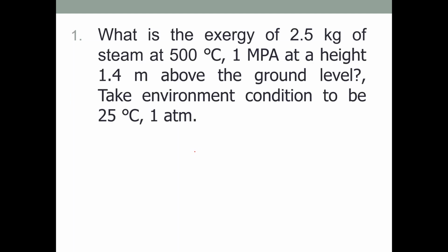Now we can apply this concept for solving different numericals. Now if you see the first numerical, what is the exergy of 2.5 kg of steam at 500 degrees C, 1 megapascal pressure, at a height of 1.4 meter above the ground level? Assume the environment condition to be 25 degrees C and 1 atmosphere.